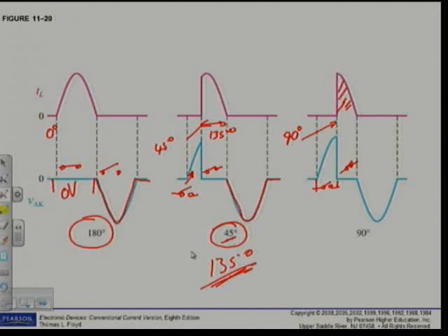That switch is closed now. There's no volt drop across the SCR. Negative cycle, exactly the same. The SCR will be off. The current drops to a value lower than the holding current, and we will get the whole negative cycle across the SCR. Everybody with me? That is basically half-wave power control of a SCR. That is one of the applications.